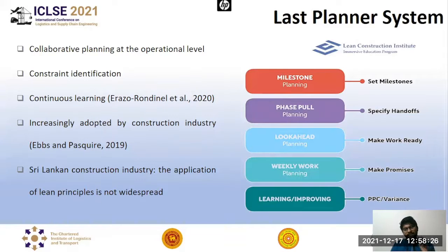In construction management, there is a tendency for project managers to assign work beyond the ability of the work crew, which leads to an average plan failure rate of about 50%. The term last planner means the person or the worker at the operational level. The last planner is in the best position to match resources to accomplish the assignment in response to downstream demand. The Last Planner System uses certain lean methods to provide improved project flow, precise workflow, and improved project control.